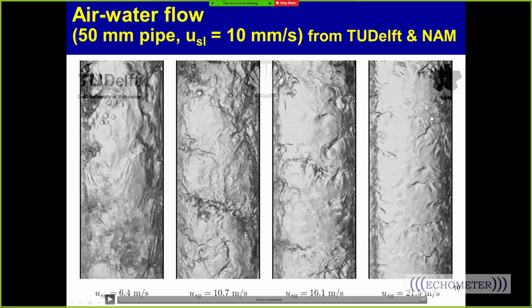In this one right here, there's probably not enough mist to block the shot. In this one over here, there's going to be a liquid level because you're below critical rate. So if there's enough mist to make an interface, you typically won't see past the top of the mist. But if the liquid is primarily on the tubing wall, then you can shoot through it.